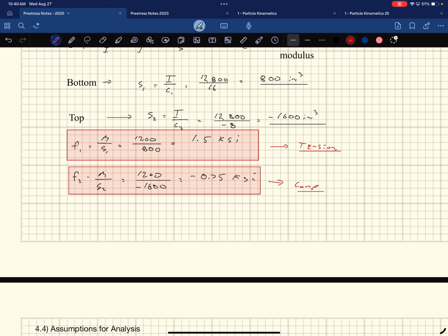We have pre-stressing stresses. You're going to have this tendon that's changing location along the length, and so some places your beam is going to be tension at the top, compression at the bottom. Other places it's going to be the opposite. Trying to keep track of all of those and making sure you're within limits ends up being pretty complicated. So this sign convention is actually really helpful for that.